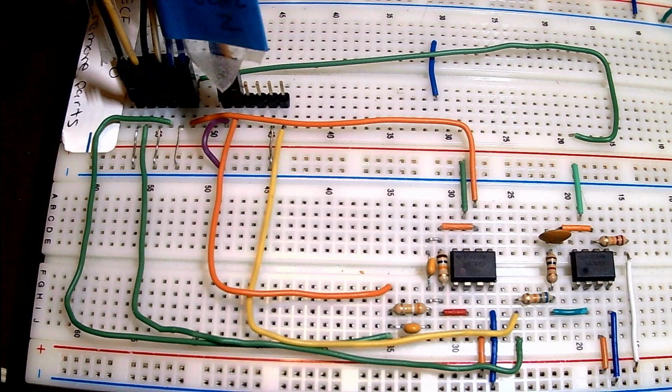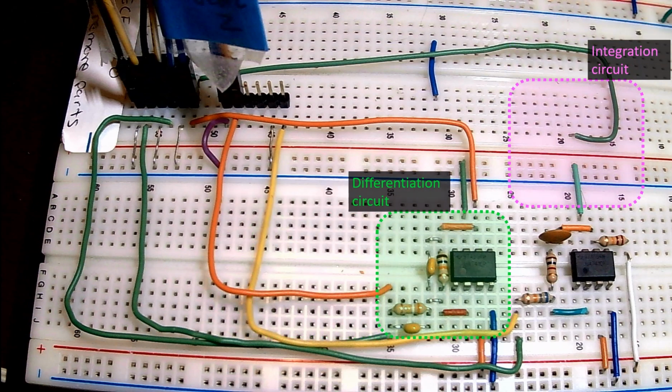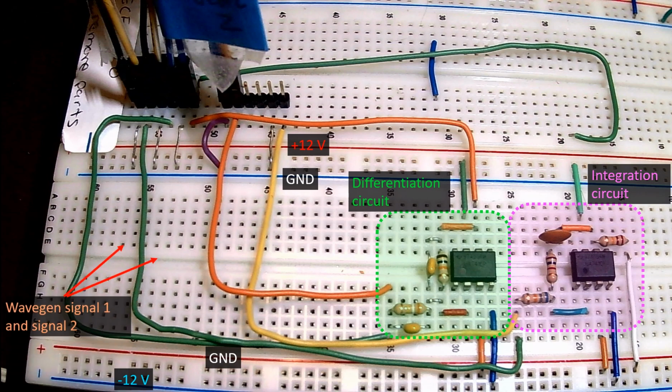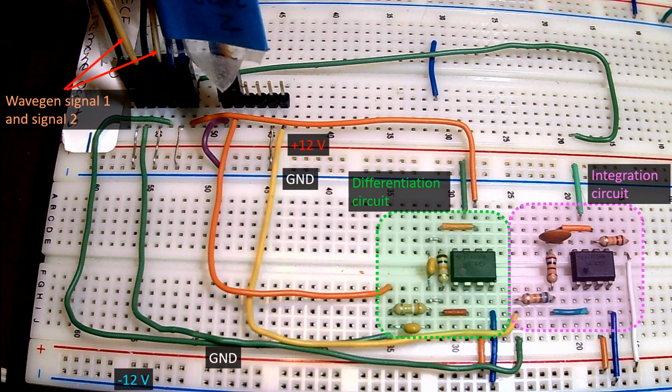This is an example of a differentiator, high-pass filter circuit, and an integrator, low-pass filter circuit. They don't have exactly the layout as in the wiring app software. Here, the plus 12 volt and minus 12 volt supplies are on two separated outer rails, and the ground are on the two inner rails. For use with the Digilent AD2, the wavegen signal 1 and signal 2 can be used as the inputs to the differentiator or integrator, respectively, or vice versa.